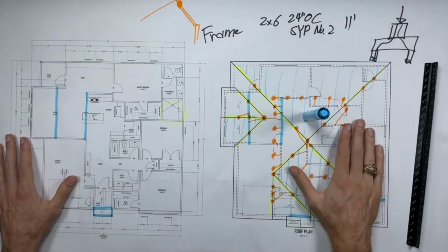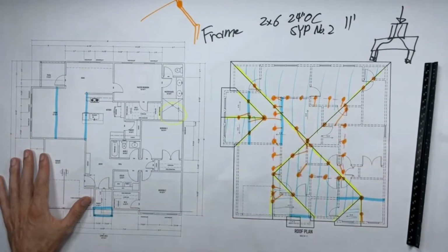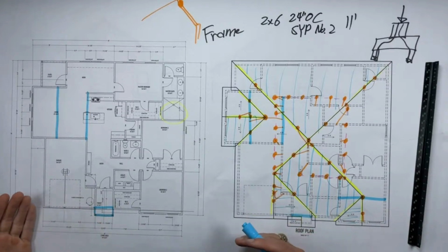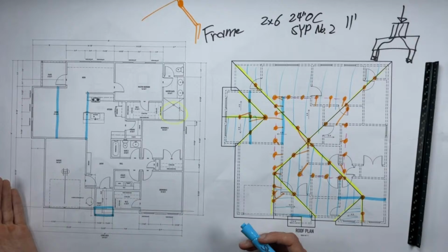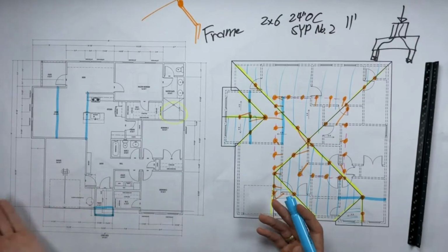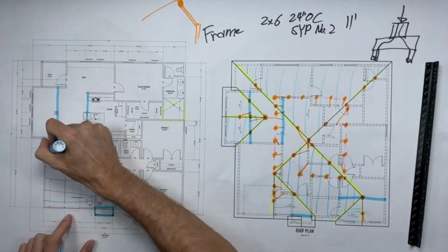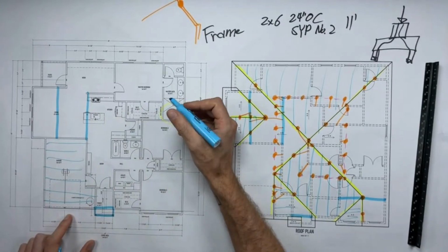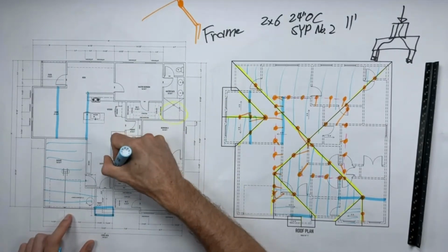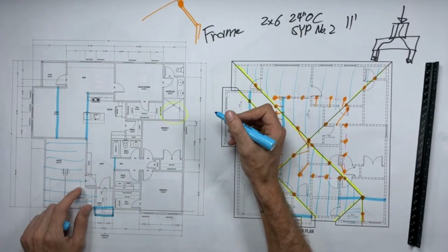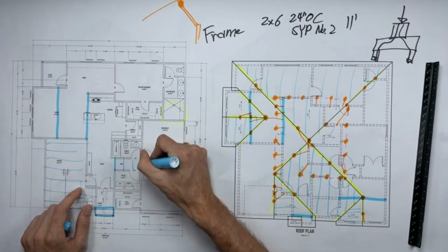All right. So roof plan, good to go. Let's talk about the ceiling. Let's look at our ceiling joists and think about how we want to do this. If it was me, I've got a lot of spaces where right to left would be a good idea. So I'm just going to run all my ceiling joists right to left. We'll do this chunk of room with ceiling joists in one chunk. If we're going right to left, I'm going to need a little tiny beam right here, some 2x6s or something, just so I don't run all the way down the hallway. And that's kind of a long hallway, so I'd probably just turn the hallway this way.